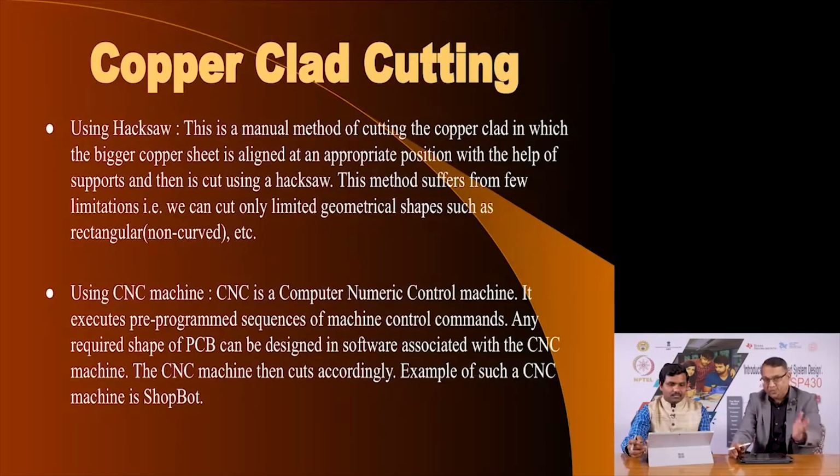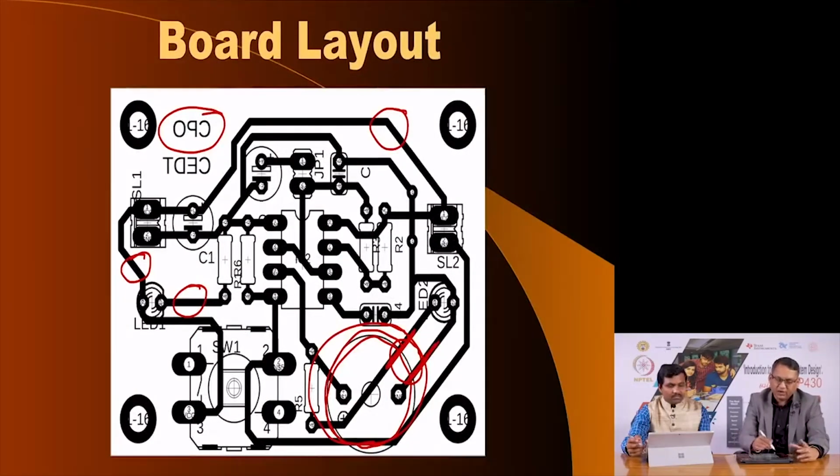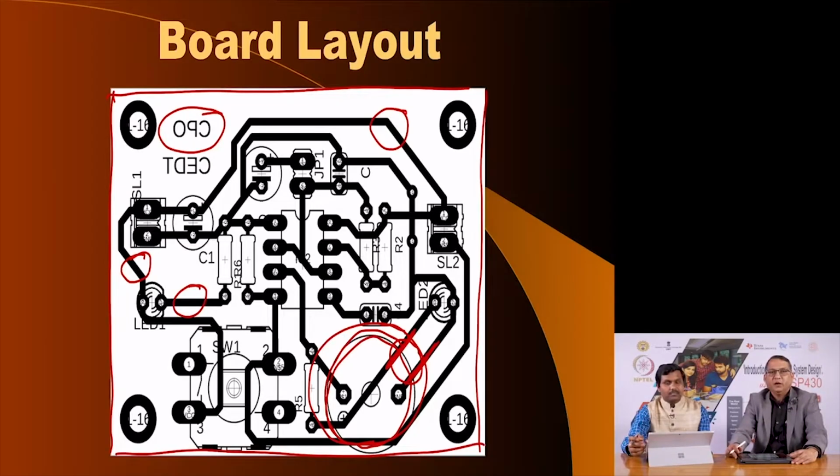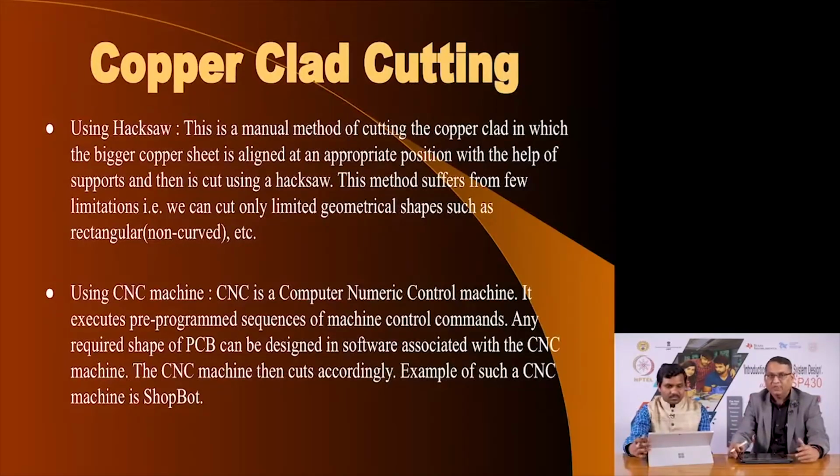Now, to prepare for the process, you need a copper clad board, and you have to cut that copper clad board to be slightly bigger than or equal to the dimension of the PCB that I wish to fabricate. Therefore, you must cut an appropriately sized piece of copper clad board from a larger stock that you may have. For that, you can mount the raw copper clad board onto your table in a vise, and then using a hacksaw you can cut it.